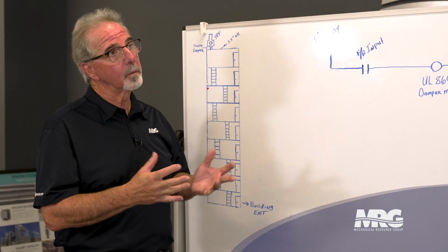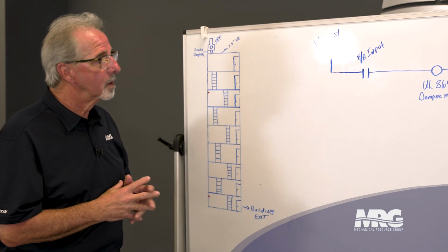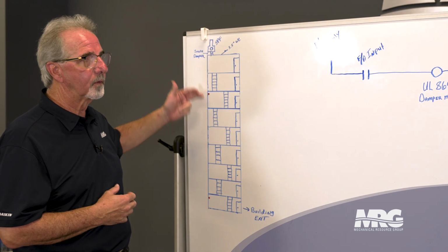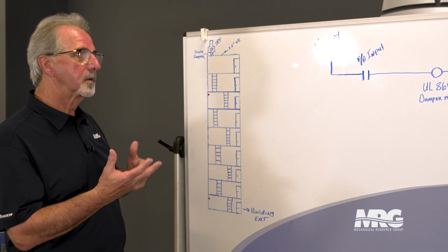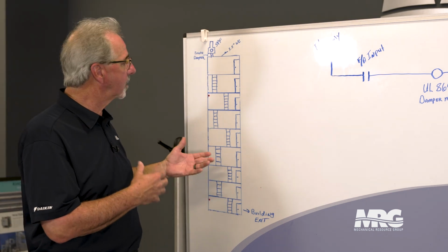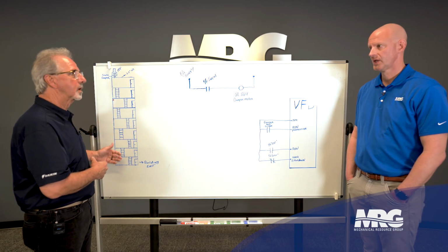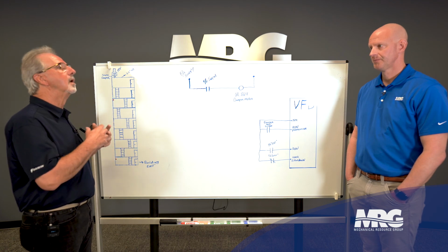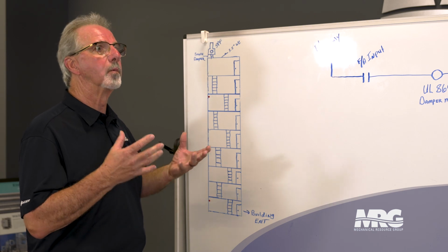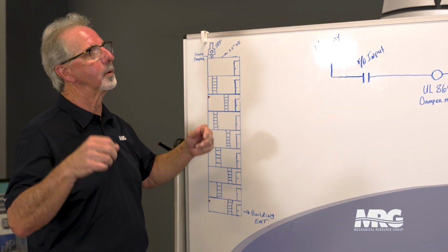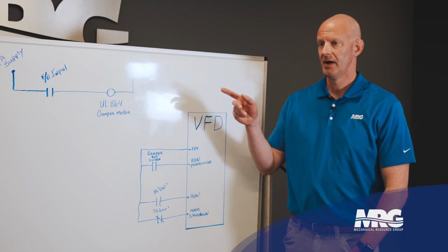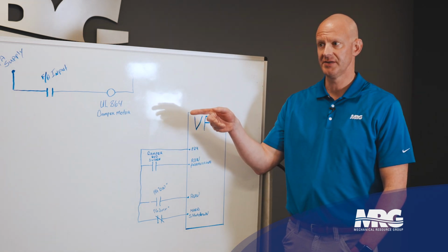Right, and it's one of the most important, because as we were talking about, it's fire life safety. So what that means, in the event, this is the only point of evacuation. And then, like I said, with the Disabilities Act, as we get on the floors, there could be people in wheelchairs, there could be people that are handicapped in other ways that can't traverse this. And so that is when they initiated, okay, let's give a dedicated elevator that could be operated under a fire condition, and we'll pressurize that, because every time the door would open, we would suck all the smoke in from the floor. So my point is, if you're building a multi-story high-rise, you're not going to get a certificate of occupancy until you get this thing figured out.